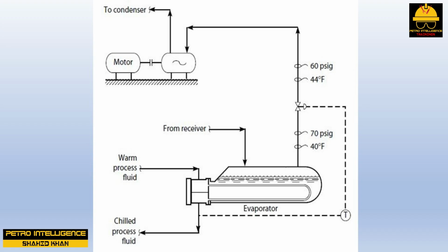On the other hand, suppose we are working with a centrifugal compressor. This particular machine has a flat operating curve. This means that a small decrease in discharge pressure will result in a large increase in vapor flow. Therefore, the load on this compressor's driver will increase. This discussion assumes that the compressor's suction pressure is fixed. However, in the real world, this is rarely the case.